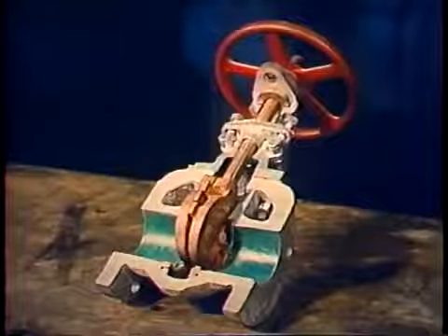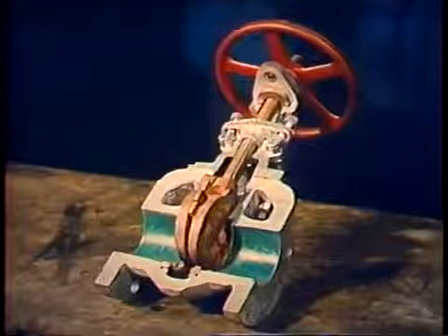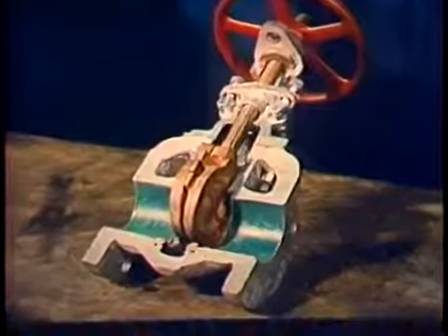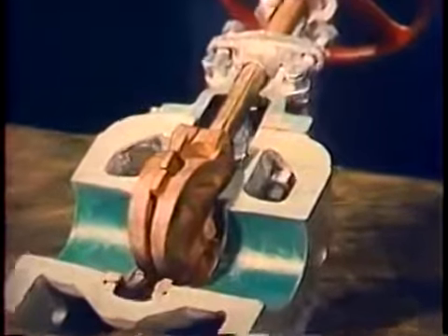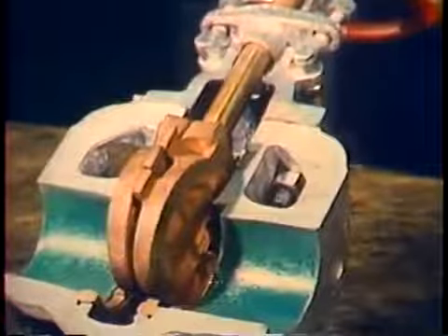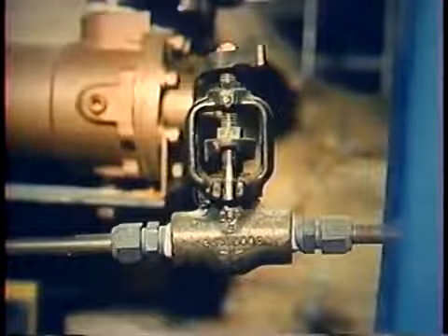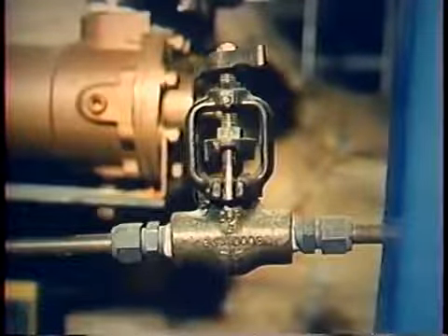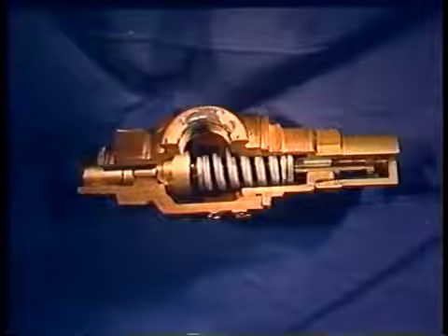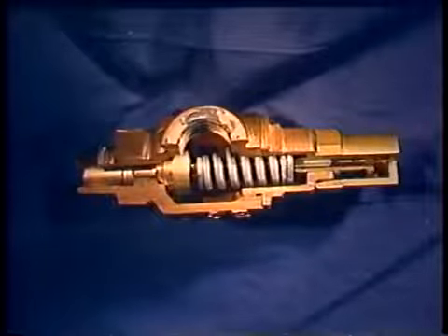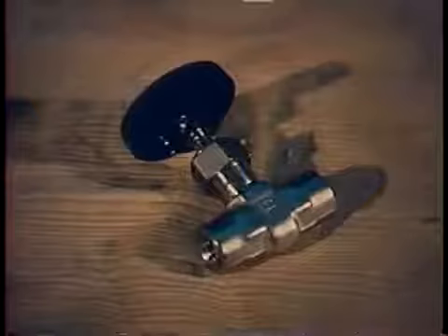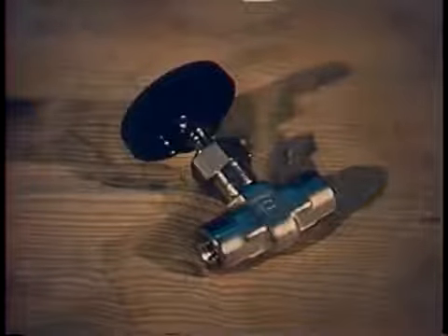Gate valves are made of various types of material depending on where they are used. For example, valves that are attached to low pressure, low temperature systems are normally made of bronze or brass. Cast iron valves are often found on low pressure steam systems or for lubricating systems. Valves used in high pressure, high temperature systems are made of special alloy metals. Stainless steel is used where there is a possibility of corrosion to the valve. You'll find a list of metals and valve applications in your text. Take a look at it.